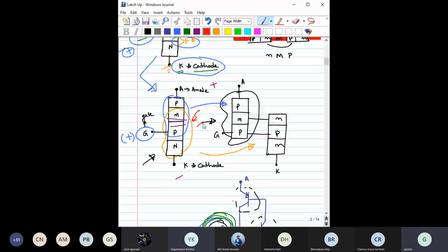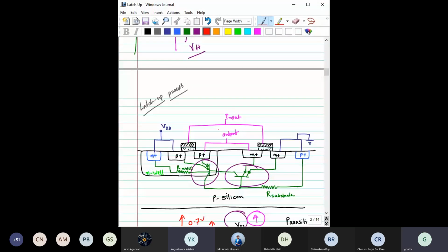Do you know what is the effect of radiation on a semiconductor? It will create a lot of excess carriers, meaning electron hole pairs would be generated simultaneously, right? And that might create an avalanche operation similar to the avalanche operation here. So again, momentarily, all of a sudden, due to the creation of a lot of additional charges, you could also see latch up operation, right? So these are the primary three reasons for this latch up.